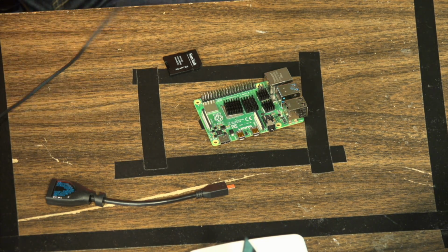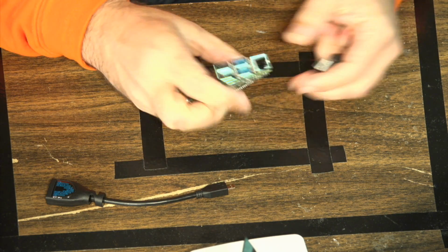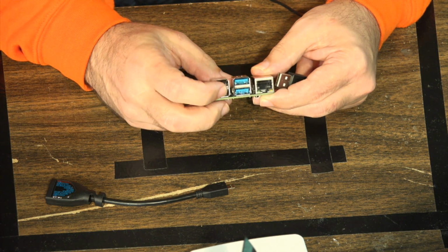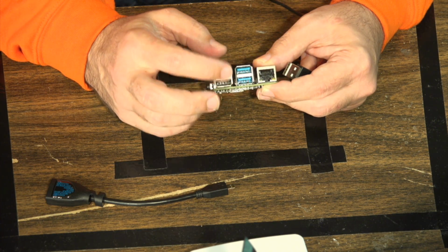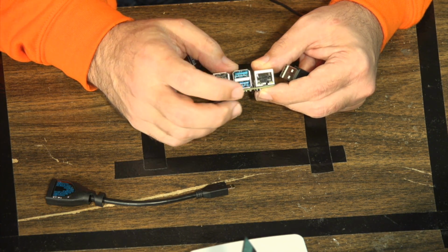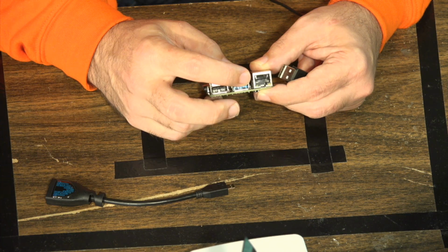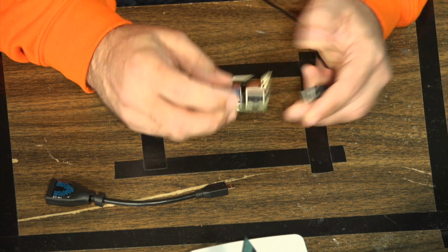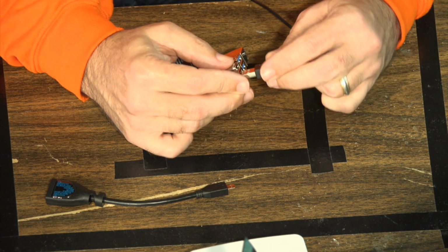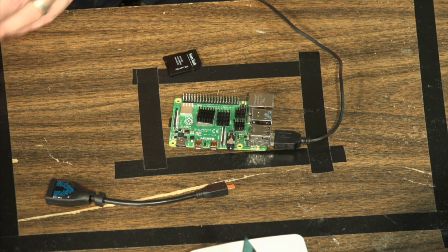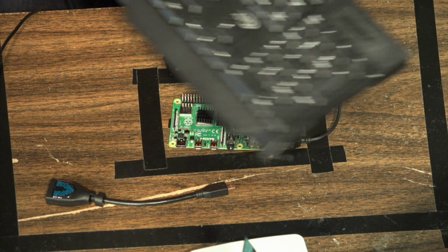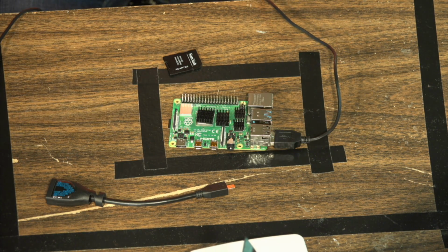So I've got a mouse here. I take the USB mouse and plug that into the USB 2 ports. Do remember, especially if you're dealing with the Raspberry Pi 4 or later versions, you have some USB 2 ports and some USB 3 ports. The USB 3 ports are the blue ports here, so you don't want to waste USB 3 ports on a mouse. So you plug the mouse and the keyboard into the USB 2 ports. I've just got a standard keyboard here, so we'll be plugging these in.